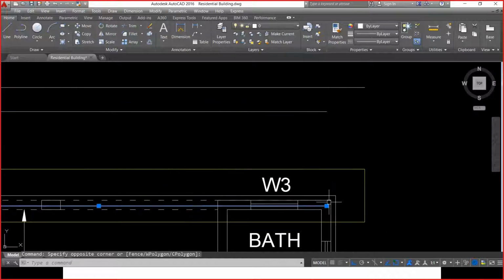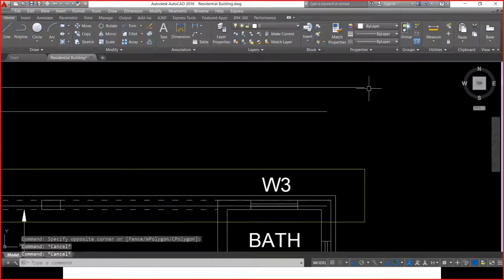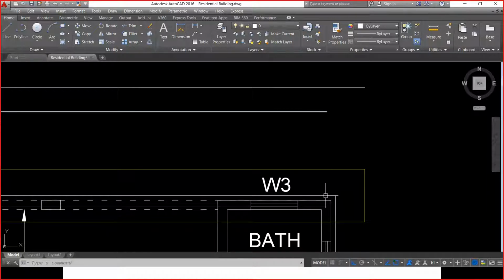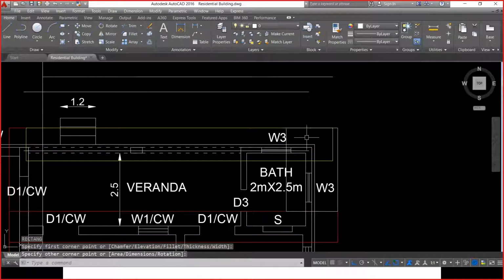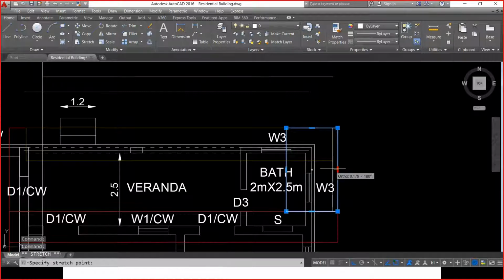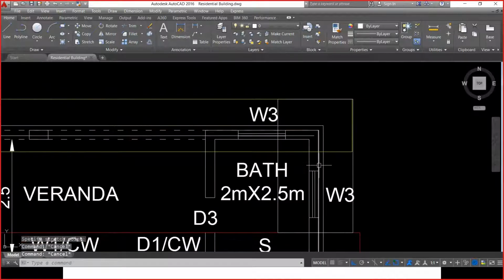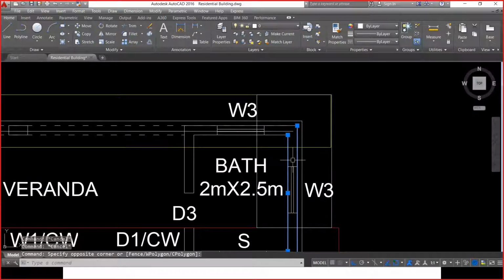Now, when I move to the other end, I have done the calculation only till here, but I want the excavation to be done till the end of the line. The end of the excavation line is over here. So what is this width? Half of this width again. I'm going to do the excavation of 0.6 meter over here. So half of this width is 0.6 meter, because for this wall also I'm going to construct 0.6 meter.